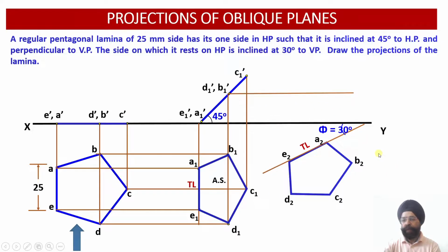Now I am drawing the horizontal lines as well as the vertical lines. Let us find the corresponding points. Just see, this is point A2. Point A2 is coming from below. Draw the vertical projector upwards. What is the projector of A1 dash horizontal? It will lie here. This will give me point A1 dash. Similarly B. So the B2 vertical projector will be coming up like this. The B1 dash horizontal projector will be obtained over here. This will give me the location of B2.